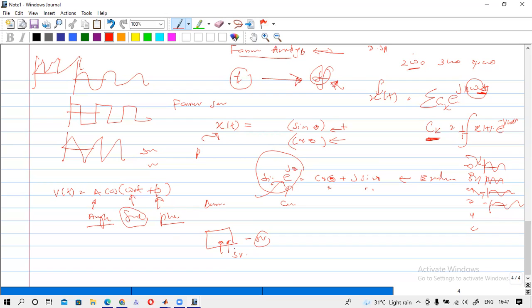Very simple. Here in the signal generator, you have plus and minus, and also there is a ground port. Can you remember? There is a ground port. So if you get a jack, and you ground this plus terminal to the ground, and if you set 5 volt, you will get the -5 here. So like this you can generate a -5 value.